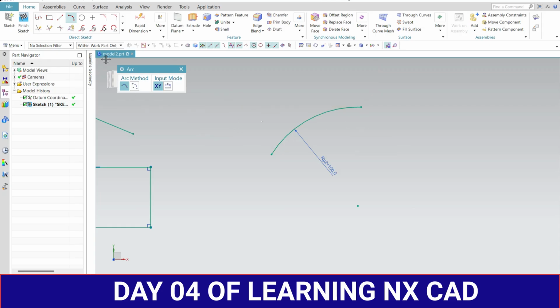So in this 3 point arc command we need to specify the 100 mm. Here, if you see, this is my first point, this is my second point, and the middle is the third point. And one more point: this is the center of this arc. Arc means it is some portion of the circle, right? So this is the center of this arc at 100 mm radius. Here we created the arc using 3 points: first, second and third.